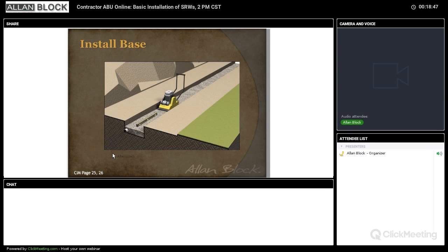So typical construction, you're going to put a 6-inch deep by 2-foot wide trench underneath your wall, and fill it with rock. In this case, we've got some illustrations to show that you don't just start compacting on top of the rock. You need to also compact the bottom of the trench to make sure you're compacting any loose material, and then start placing the rock in the trench, compact it. Get it pretty level, okay?